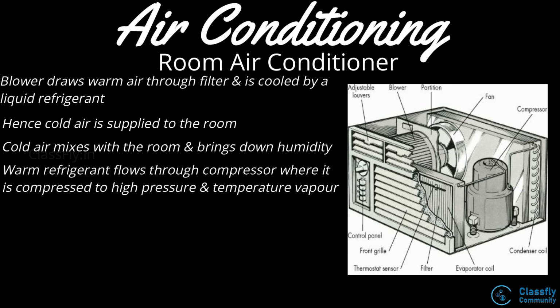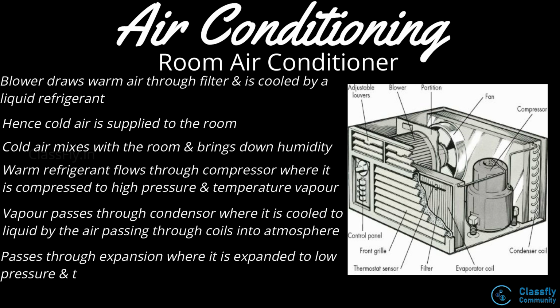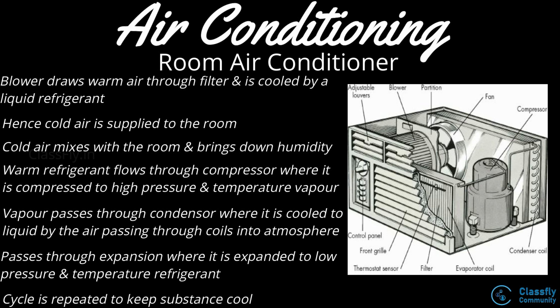Well, the refrigerant which absorbed the heat from the warm air now flows through the compressor where it is compressed and then enters the condenser where it is cooled into liquid state. The fan draws and blows the atmospheric air over the condenser coils and hence the heat is now given away into the atmosphere. Now the refrigerant enters the expansion valve and is expanded back into a low pressure and low temperature liquid refrigerant. The same cycle is repeated in order to keep the room cool.